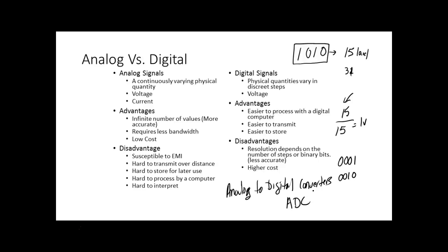We deal with such an analog world that a lot of your programmable controllers, and these are computers that are designed to run machines, most of them now come with at least 1 analog input. When they come in, they're going to run into an analog to digital converter, and then that converter is going to take that analog value and somehow convert it over to a binary number. The 1100s that we deal with use 10-bit analog to digital converters.